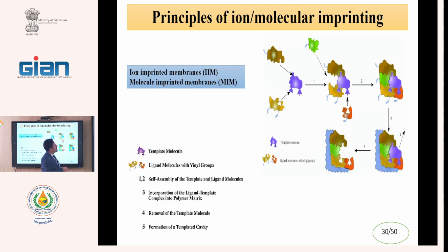For preparation of this structure, we must use network polymers. Network polymers mean that between the chains of polymers, we must cross-link, because with a change of temperature, the imprint should be stable. And for a stable configuration, we use 3D polymers.